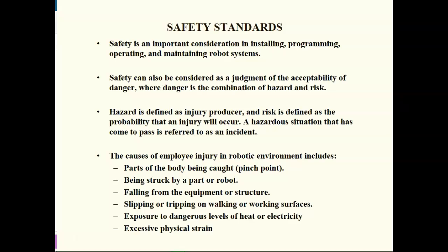So the causes of employee injury in robotic environments include parts of the body being caught in pinch points. That would be where, if it says don't put your fingers there, they generally have got warnings on most robots. Pinch point. Don't put your fingers there if you do not need to. Be aware that that is a pinch point. Being struck by a part or robot. Yeah, that happens quite frequently.